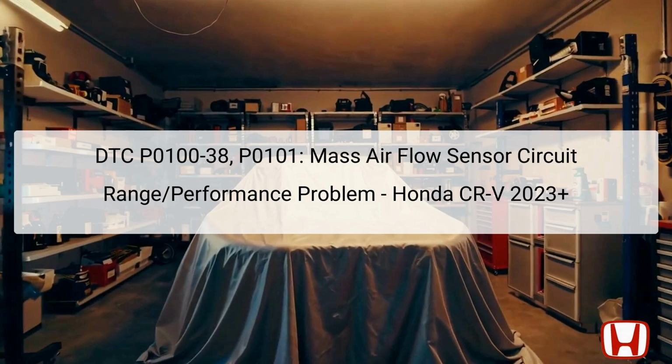Welcome to the troubleshooting guide for DTC codes P0100-38 and P0101, which pertain to the mass airflow (MAF) sensor circuit range and performance problem, specifically for the Honda CR-V model from 2023 onward. When the powertrain control module, PCM, detects that the output frequency from the MAF sensor falls outside a predetermined range, it logs these diagnostic trouble codes.